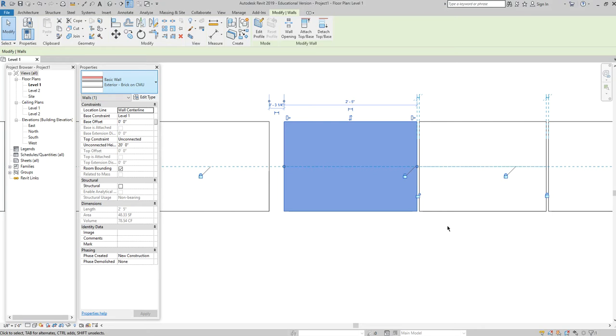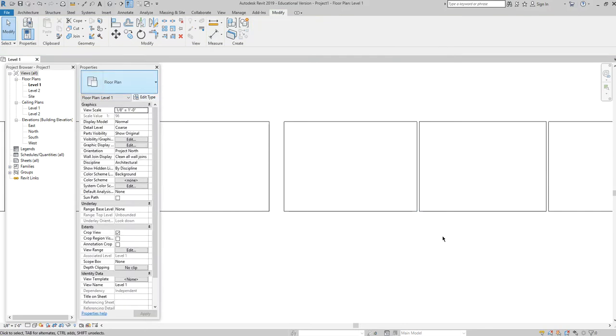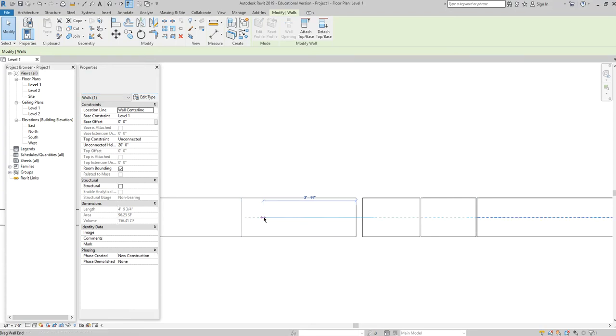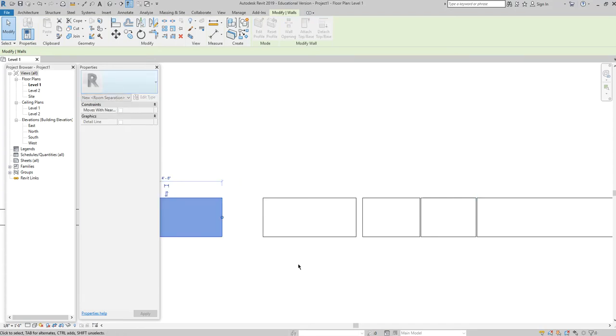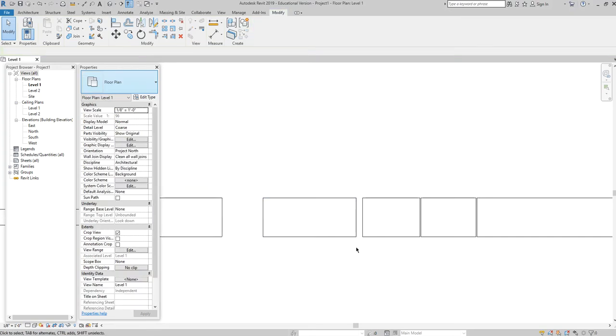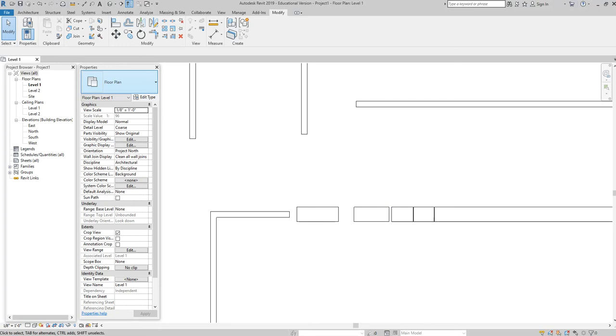Why is it being sticky? You won't run into it hopefully for a while, but that's the reasoning why I will usually use split with a gap. If my split is being kind of sticky and won't allow me to pull the elements apart or change them independently, which it should, I'll use split with a gap to put a physical barrier between those two objects, in the form of space that I can then move apart. So splitting with a gap is fairly easy.